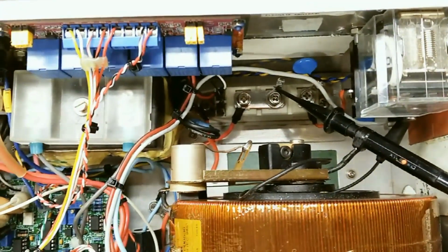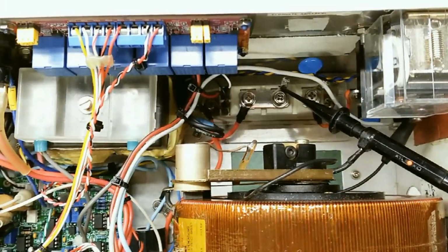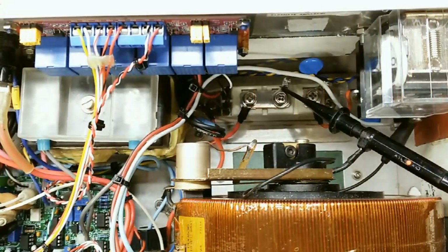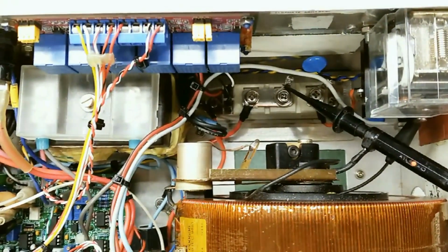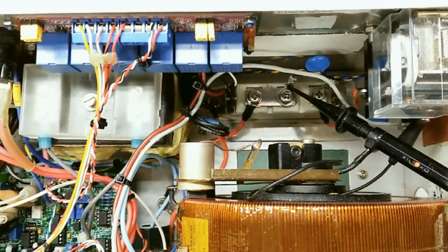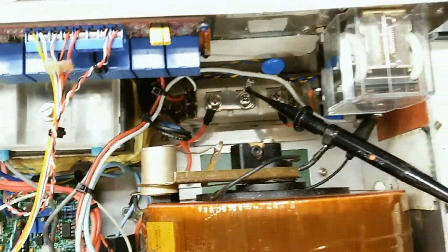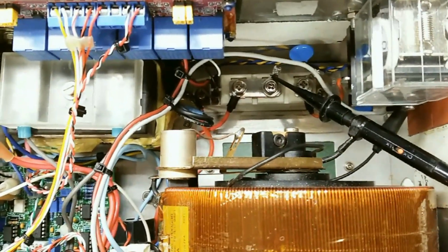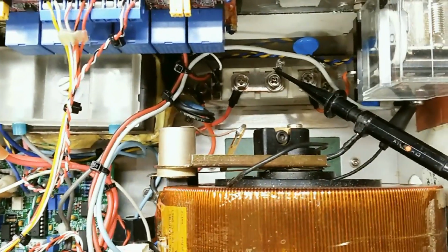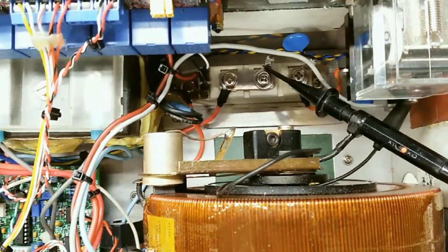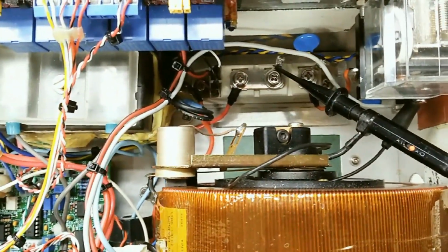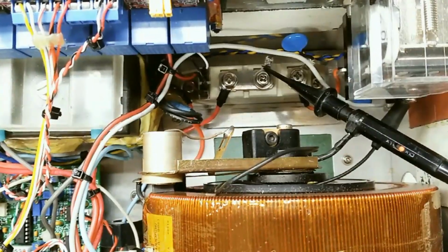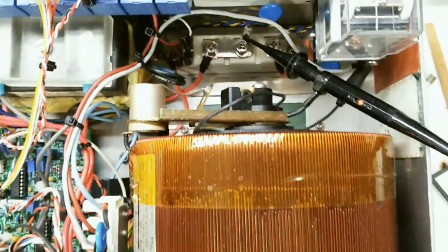It must be because of the back EMF affecting the gate circuit. I'm not exactly sure 100% how you can solve it, because I've tried many things and I cannot really solve the issue. But I have improved it. And the improvement is by changing the resistor on the gates, on the gate circuit. And I'll show you that now.